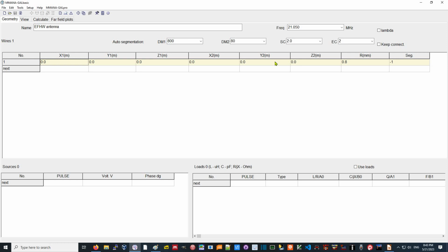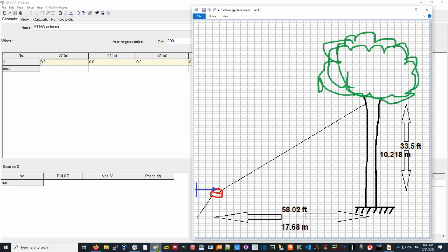So here we're going to go ahead and put in some values. What values? Well, let's look at our geometry. Our field geometry, or what we expect to have, is an antenna that is going to have a 49-to-1 transformer here, a little pigtail, which is actually going to be this counterpoise, or really it's going to be the sheath of the coax cable. This is a coax cable going to our radio. The radio would be down here. This is the 67 feet long wire that I'm going to perch up on a tree.